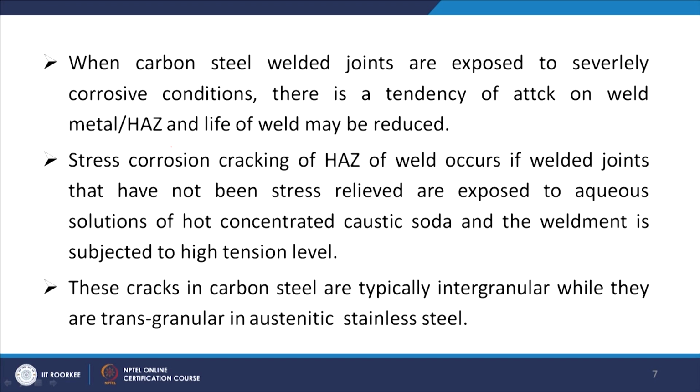Now, that is what we have studied: stress corrosion cracking of HAZ of weld occurs if the welded joint has not been stress relieved and is exposed to the aqueous solution of hot concentrated caustic soda, and the weldment is stressed in tension to a very high level.